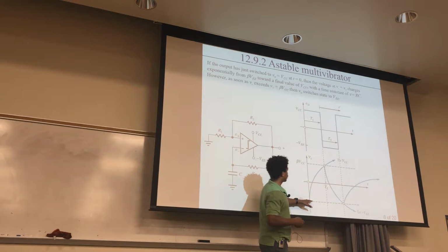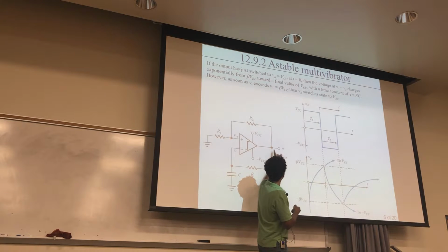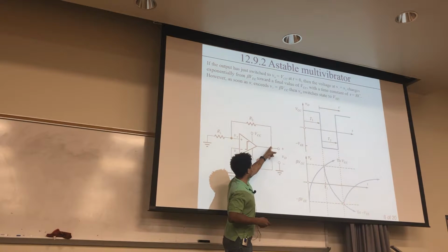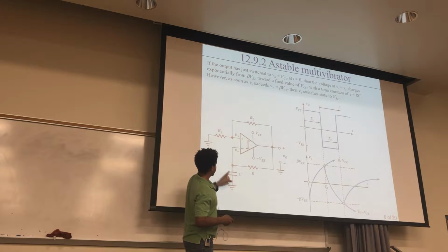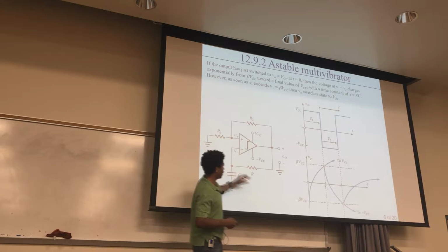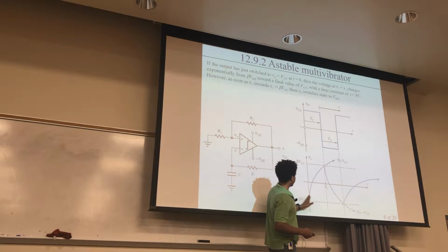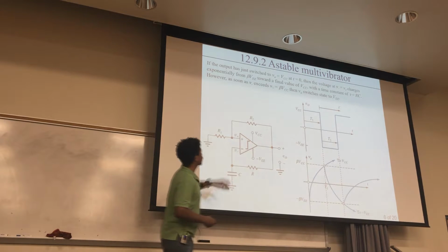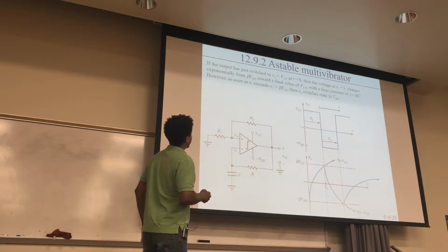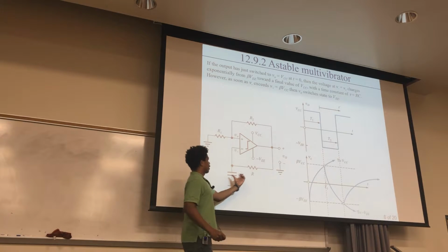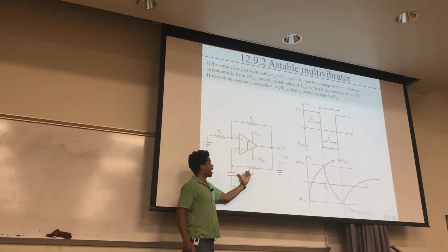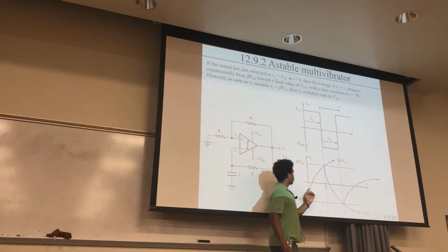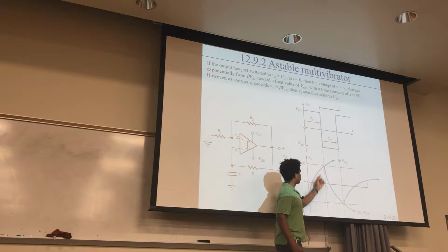So you're down here, then as soon as you switch to VCC, that's going to be VCC right here, and then this charge right here is going to start climbing from this negative beta VEE toward VCC. It's going to asymptote to that value. Okay, so that's what happens. And it does so at a time constant of tau equals RC. So this is the time constant. And that's how you can actually adjust your period of change, right? Before it starts switching and going the other direction.